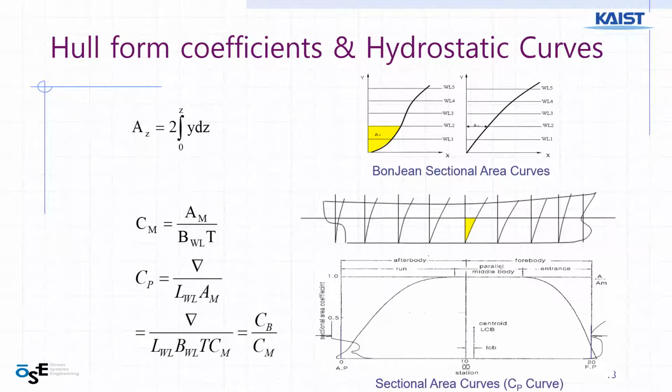No question. So hydrostatic curves give you the fullness of the ship, the coefficients calculated, and also the most important thing is that the volume of the ship can be calculated by the section area. So this was tough work in the old days for naval architects.